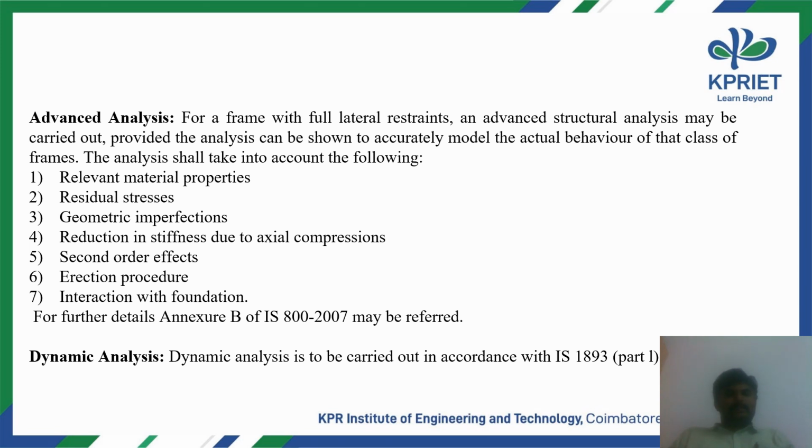The analysis shall take into account the following: relevant material properties, residual stresses, geometric imperfections, reduction in stiffness due to axial compression, second order effects, erection procedure, and interaction with foundations. And the last one, dynamic analysis, is to be carried out in accordance with IS 1893 part 2.